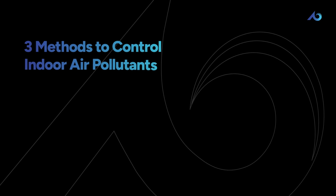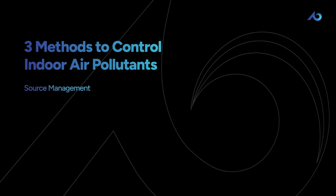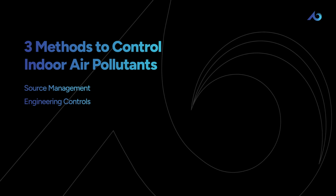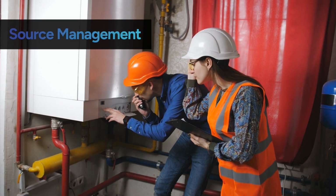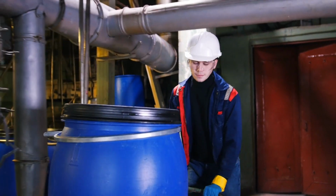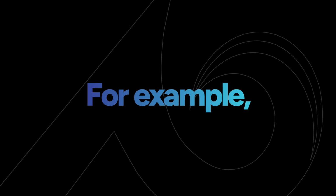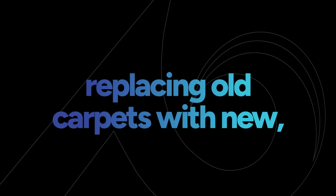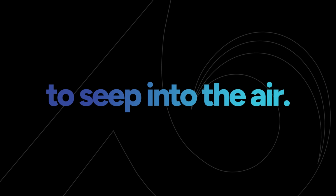There's 3 basic methods used to control indoor air pollutants: source management, engineering controls, and administrative controls. Source management involves isolating the issue at its source. This includes isolating, removing, or substituting hazardous materials. For example, replacing old carpets with new, green label carpets that have fewer chemicals to seep into the air.